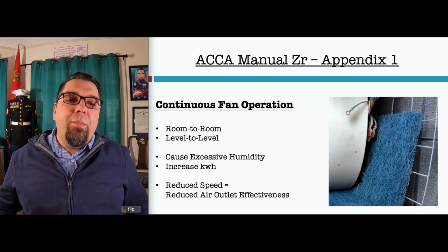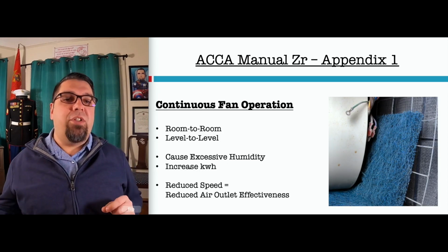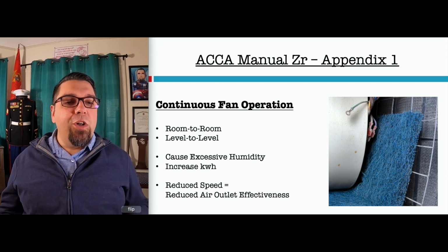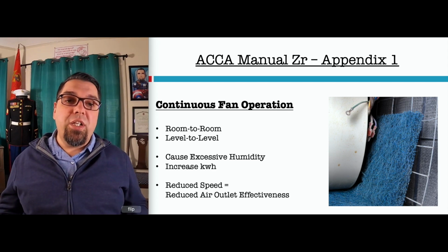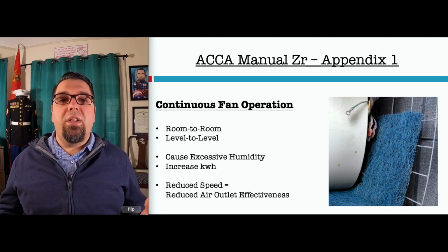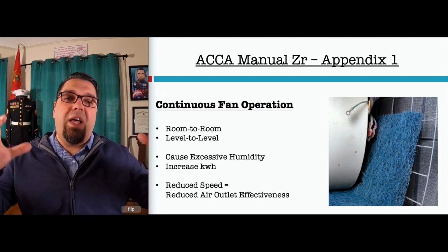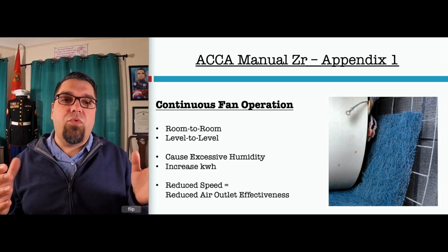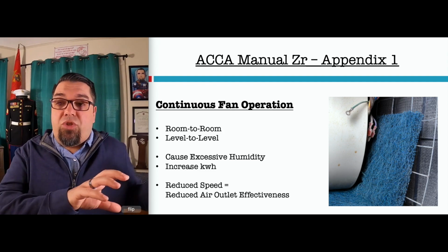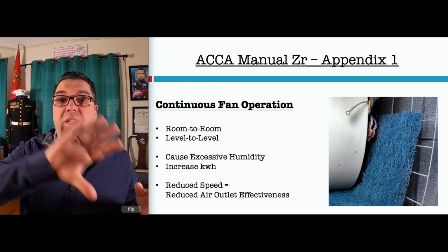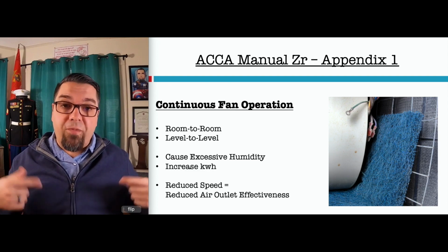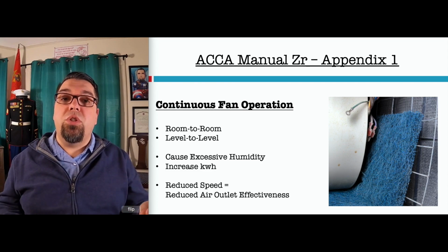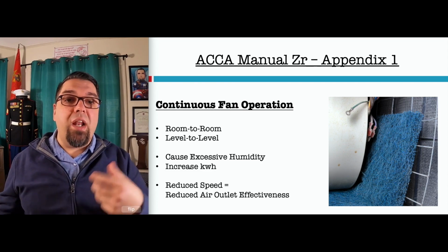One of the common methods for a service tech when they have big temperature differences across floors or rooms is to just run the fan constantly. Unfortunately, when you do this, a lot of times in air conditioning, in cooling mode, you're gonna end up not cycling the fan off and letting the moisture drain off the coil. What ends up happening is when the air conditioner shuts off and the fan continues to run, you actually redistribute that moisture back into the air and you start pushing that moisture back into the space. Obviously, when you're running the fan all the time, we're gonna increase the electrical usage as well. So this is a temporary solution to a bigger problem, and it's just gonna create other issues, right?